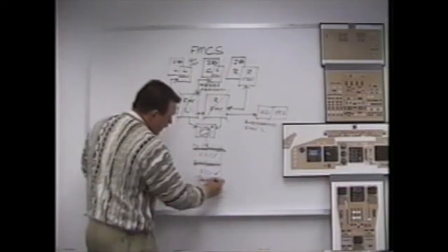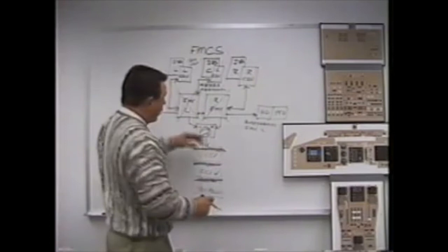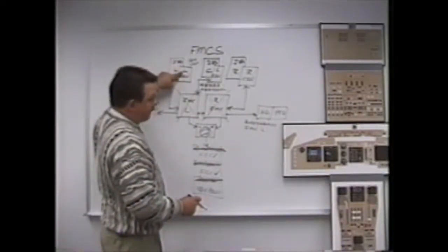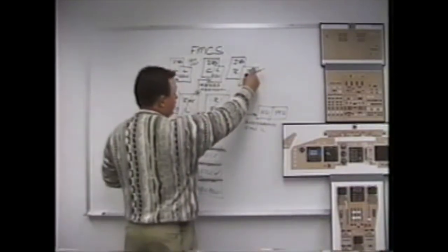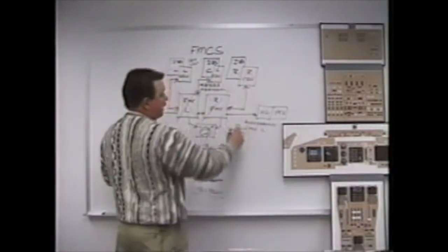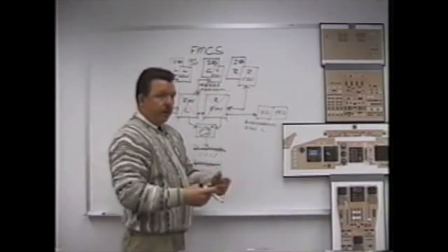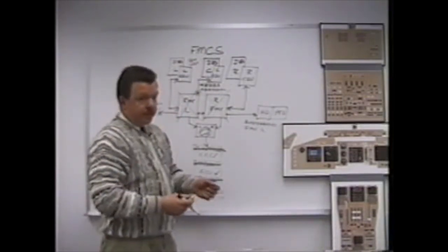The auto-tuning of the nav radios is gone. The nav radios will still work, but you have to manually tune them. In fact, you will manually tune the left VOR, the left ADF, and the left ILS on the left CDU. You'll tune the right radios, VOR, ADF, and ILS on the right CDU. You need to go to the center CDU and tune the center ILS if you expect the center autopilot to fly the approach. Can you do a Category 2 approach in this case?